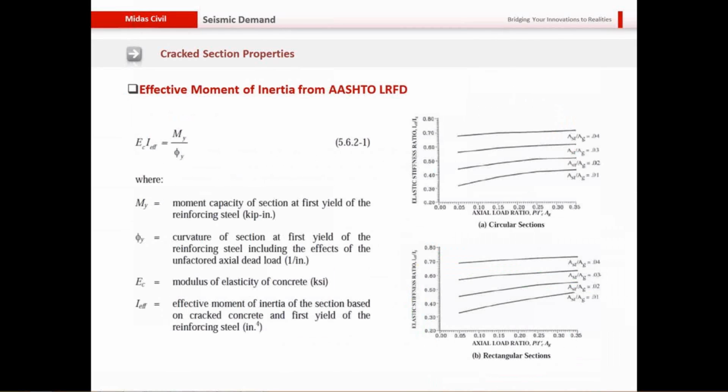The same provisions under the AASHTO LRFD actually give slightly less conservative values. It is almost exactly the same formula, but the Eurocode adds 8% of the uncracked section stiffness to it. An additional provision in AASHTO LRFD specifically for RC box girders is that you can assume the values are anywhere between 50% to 75% of the uncracked stiffness. But for pre-stressed box girders, it is recommended that no reduction be applied.